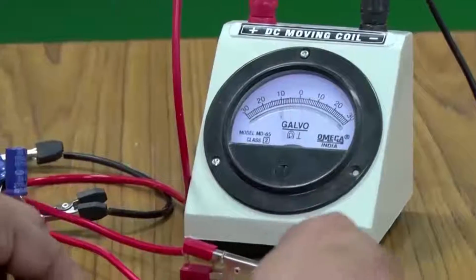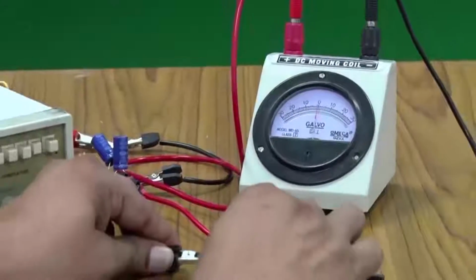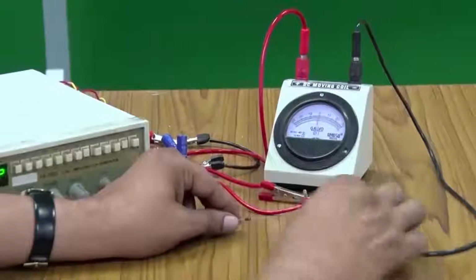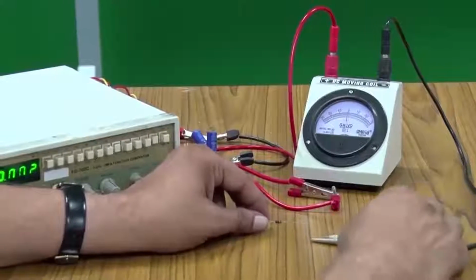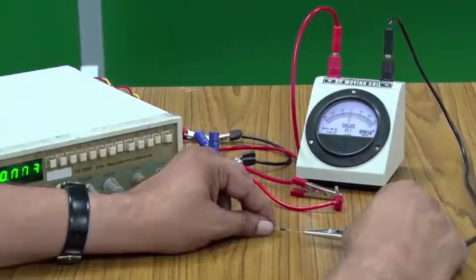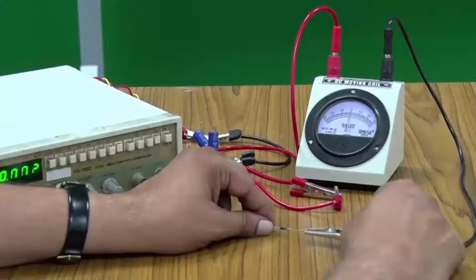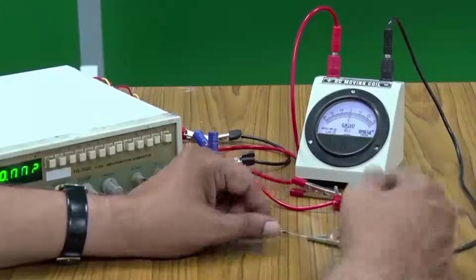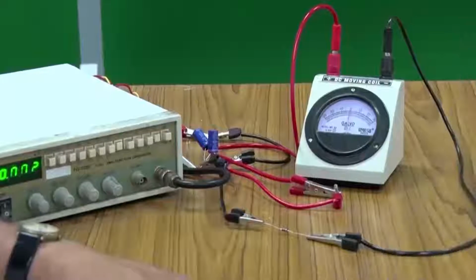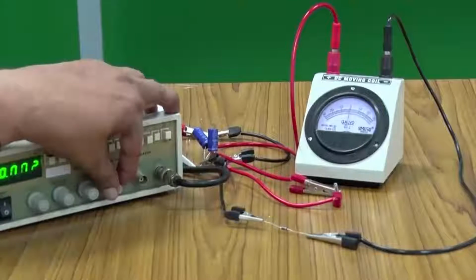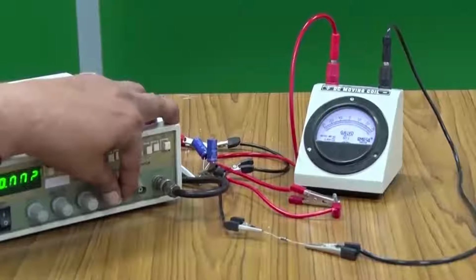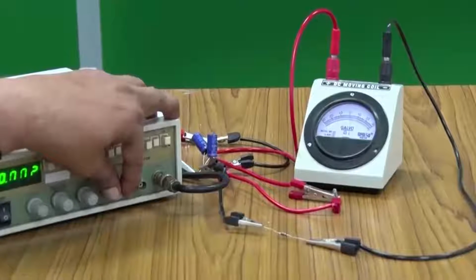So, that shows that this assumption that we had taken, that just forward bias and you have large current, is not true. You have to supply some initial voltage, after which the IV characteristic, the exponential part, starts, only then it works. So, let me increase this voltage and you can see that yes, now it has started going.